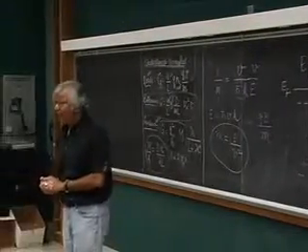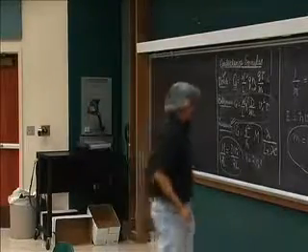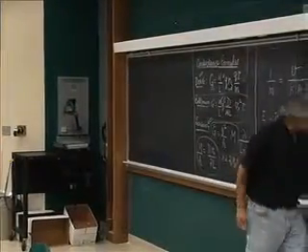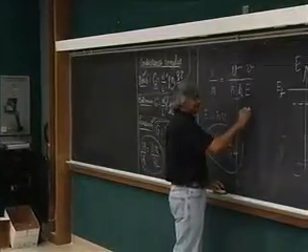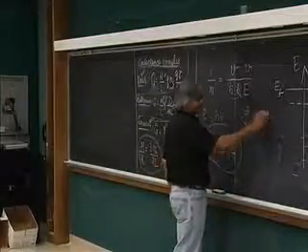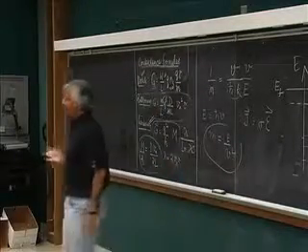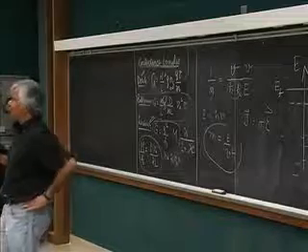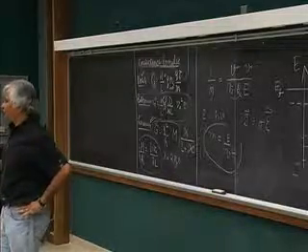And one point I keep making often is that you tend to say J equals sigma E. That is, current is driven by an electric field. And the point I make is that's really not true, because in a PN junction, there's an enormous electric field, yet no current flows.